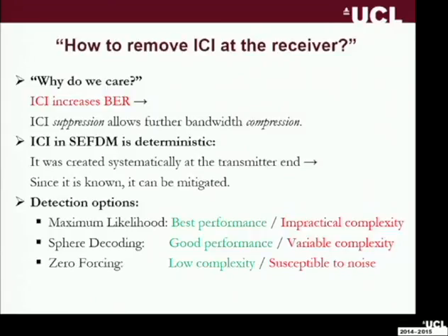So zero forcing is not new. It's an equalizer used for channel equalization, where you invert the channel to counteract what's happening in the multipath fading. So we thought, we've kind of got a channel here. If you consider the SEFDM self-created interference between the subcarriers, we can visualize a channel matrix from it, which is deterministic. We can actually compute that. So we thought, okay, let's apply zero forcing, just invert the interference we've created.